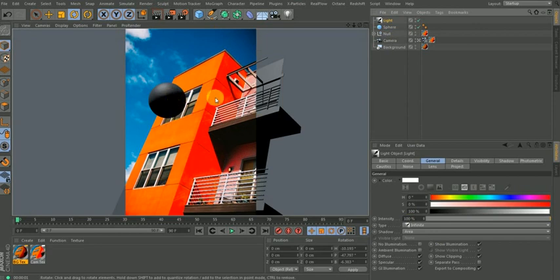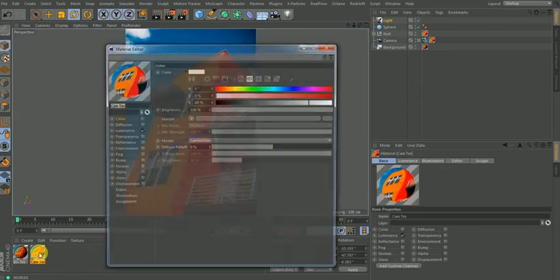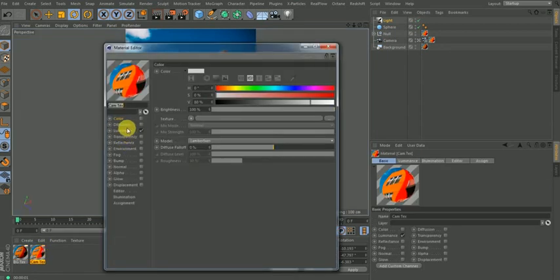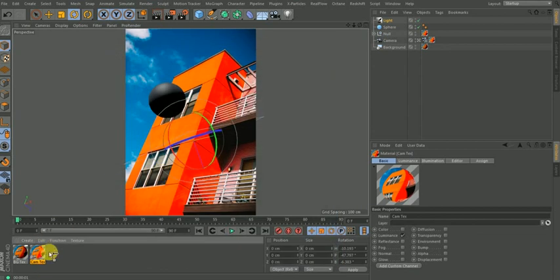Now I found the solution to this is just to create a new tag. Don't forget, on our object we added the camera texture. Now if you open the camera texture, the only thing we have is just luminance. So luminance doesn't receive shadow. So what I do is to have a duplicate of this, then call this object or building asset, then double click the building asset.